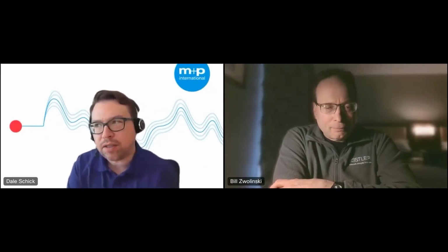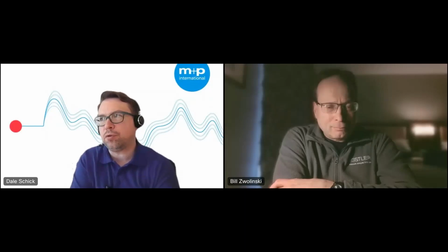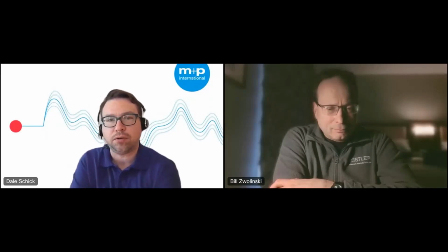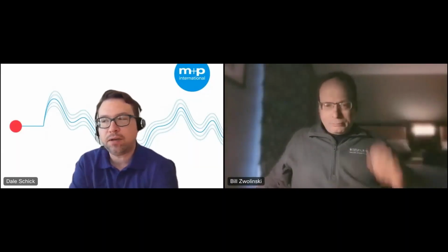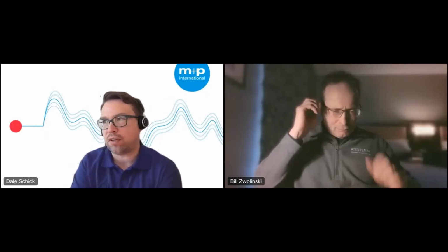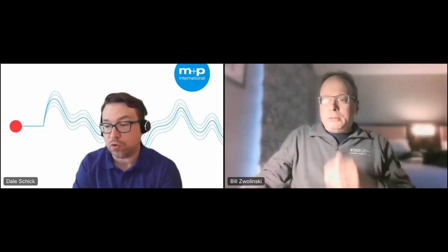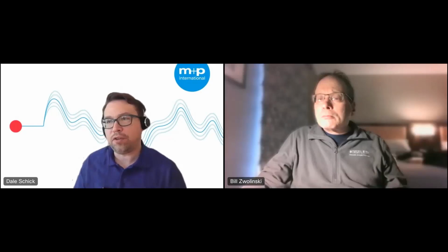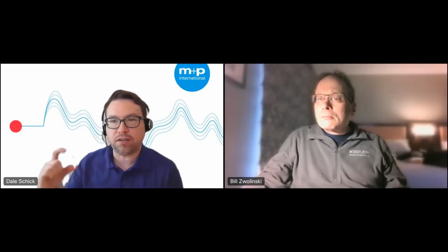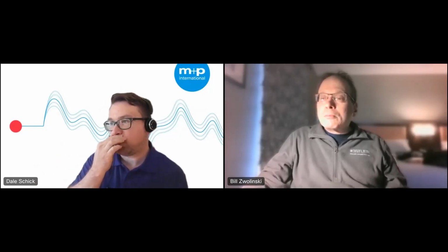Yeah, and I think additionally, the only risk that I would see is if your fixture were not stiff enough and your fixture resonance has started to creep into your test range. This is where doing a good FEM, doing a good modal test on your fixturing beforehand can really help to determine what's usable on the fixture. On my system here, I do have the accelerometer mounted very near to the force sensor, but it's really just because I don't really have anywhere else to put it.